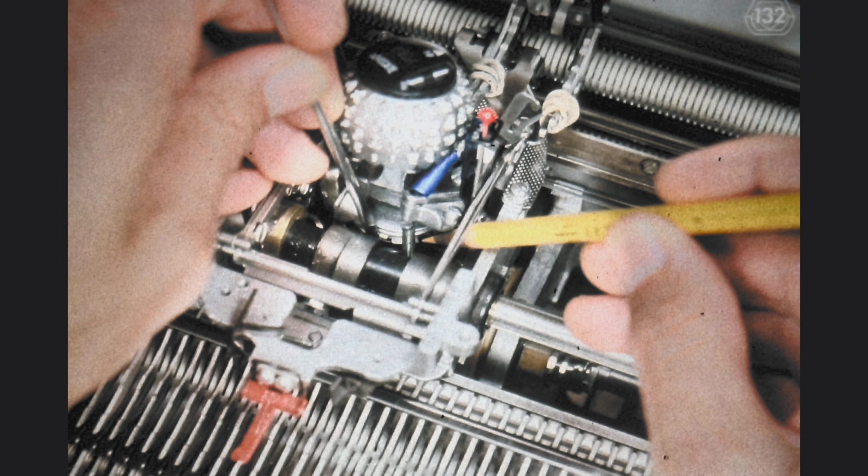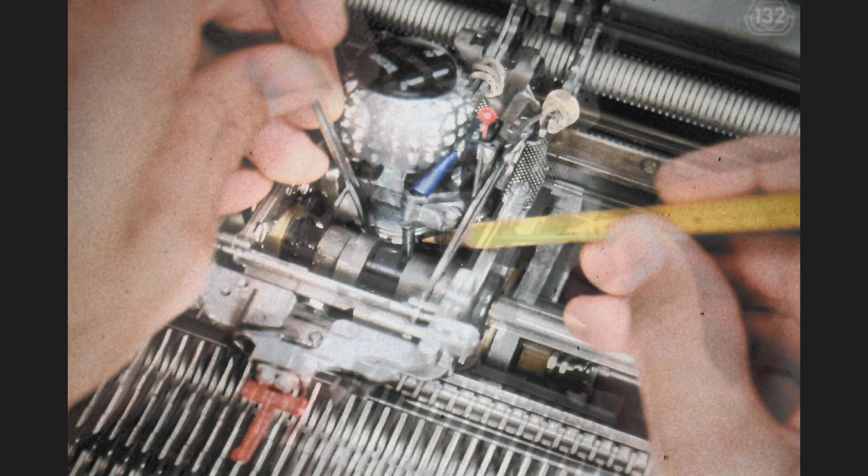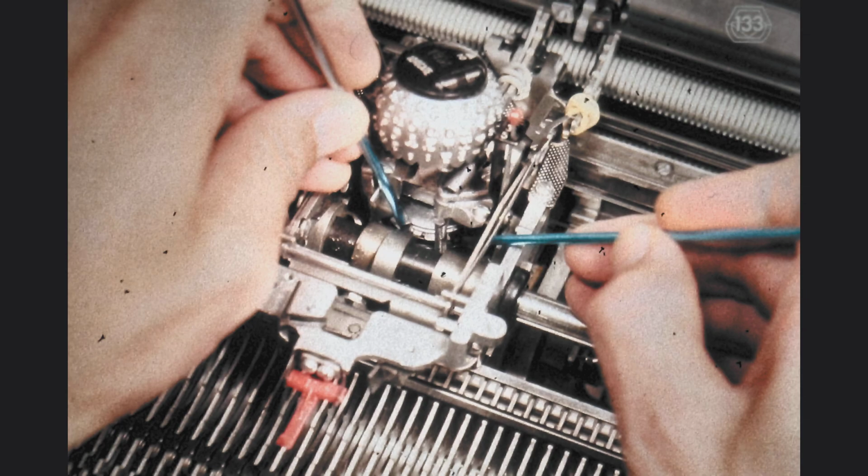If, however, we want to decrease the spring tension, we must use another tool to control the spring cage and then go to the spring indicated by the yellow pencil. Hold it out of the way of the rotate spring cage while allowing controlled amounts of counterclockwise rotation of the spring cage. When you take the ratchet spring out of the way of the spring cage, be very careful not to force or bend the little spring. The rotate mechanism is very likely to sustain damage if you let the spring tension escape all at once.